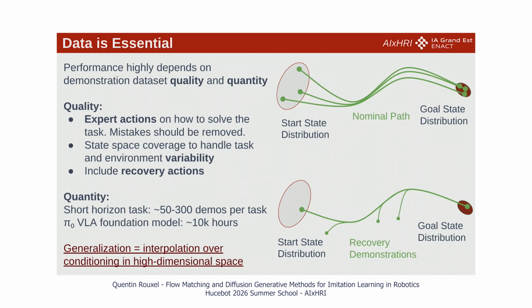And actually, this is very hard to do, because when you do the teleoperation, you have to keep in mind that you need to reset the environment to this state, and this state, to show the robot how to recover from that. Because if you're just showing what to do when everything goes well, when you are too good an expert, your policy will get very brittle, not robust to anything that can go wrong. So adding this recovery demonstration is very important for the quality of the demonstration.